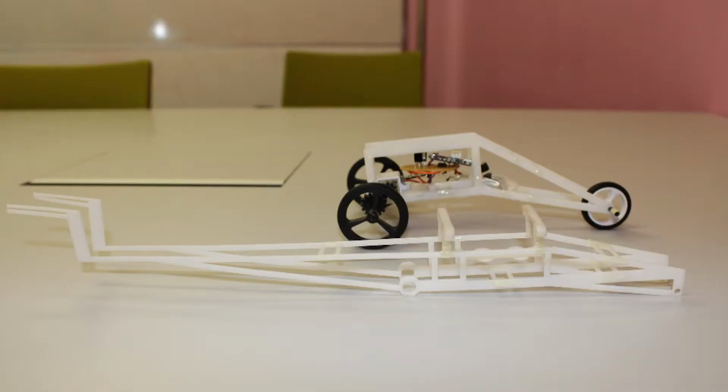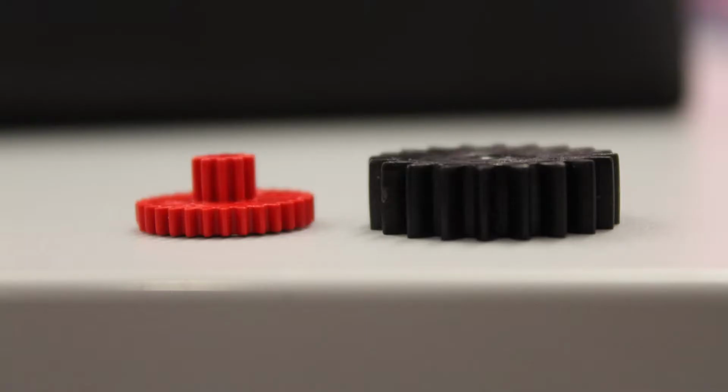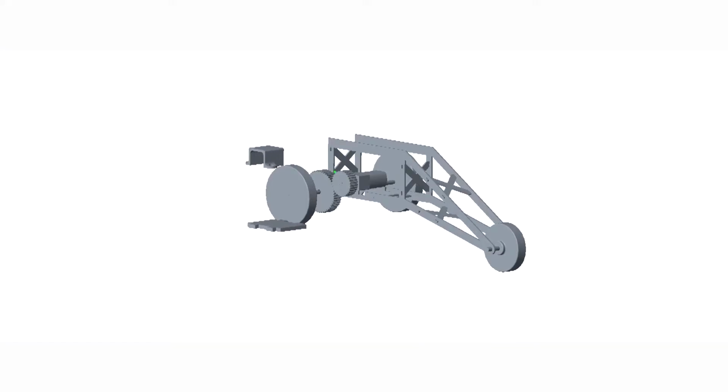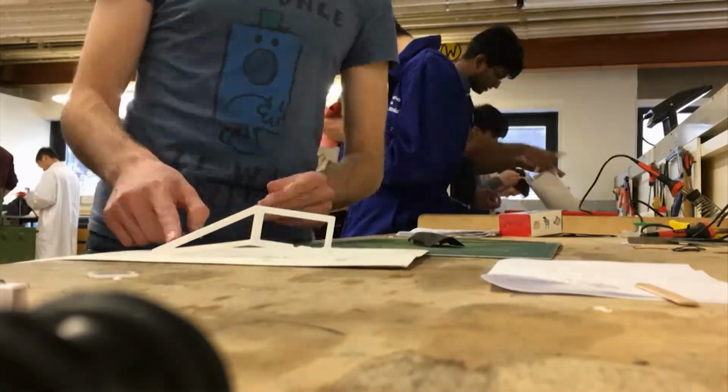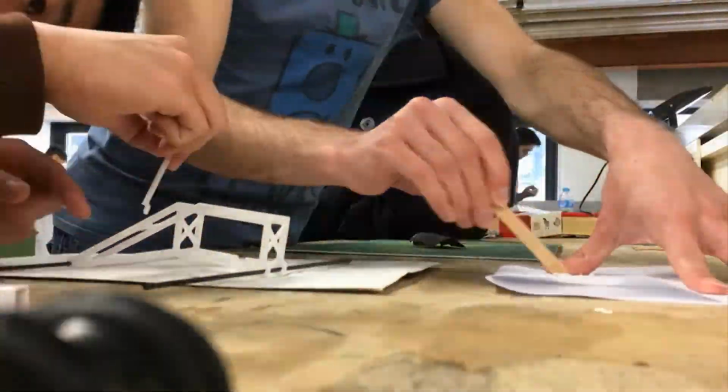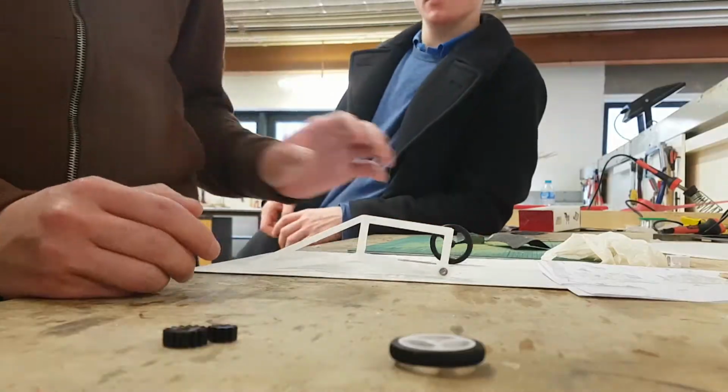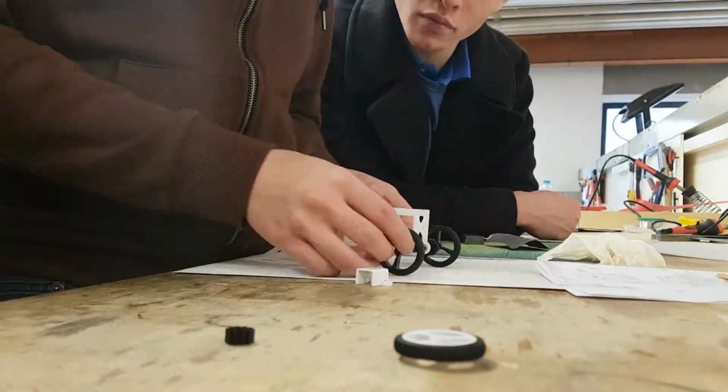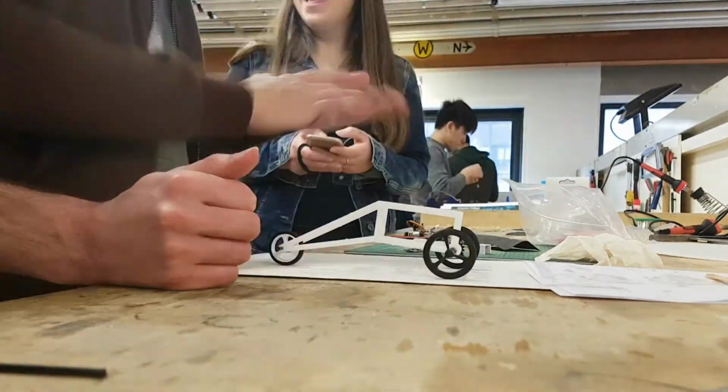In this improved design, the tail of our structure was removed, saving weight and eliminating the chance of tail strike. Stiffness was also improved, making our structure torsionally stiffer and more resistant to impact damage. One key improvement we made was to use wider gears, making gear interaction easier and therefore solving the unmeshing issue. Rather than using an interference fit for the motor, we decided to install a motor bracket, thus improving the motor-axle connection. The second fabrication process was much easier this time, as many of the steps were similar to the first iteration. A larger wing was manufactured to give us more lift. This was possible only because of the weight reduction that came with having a shorter undercarriage.